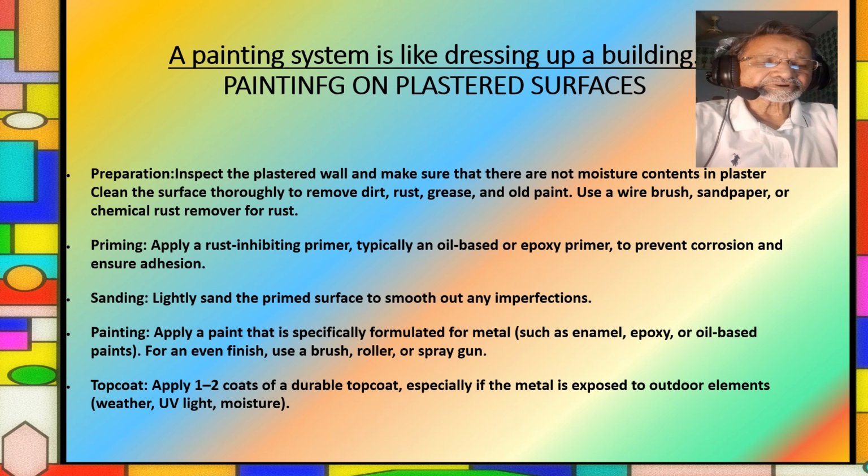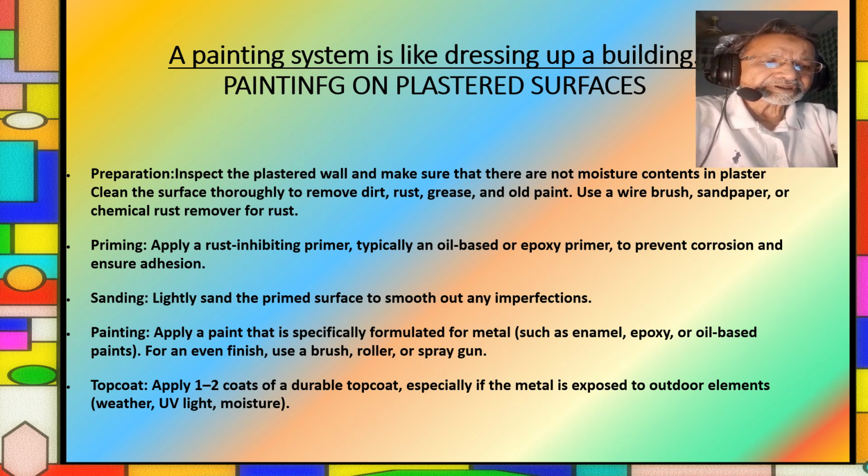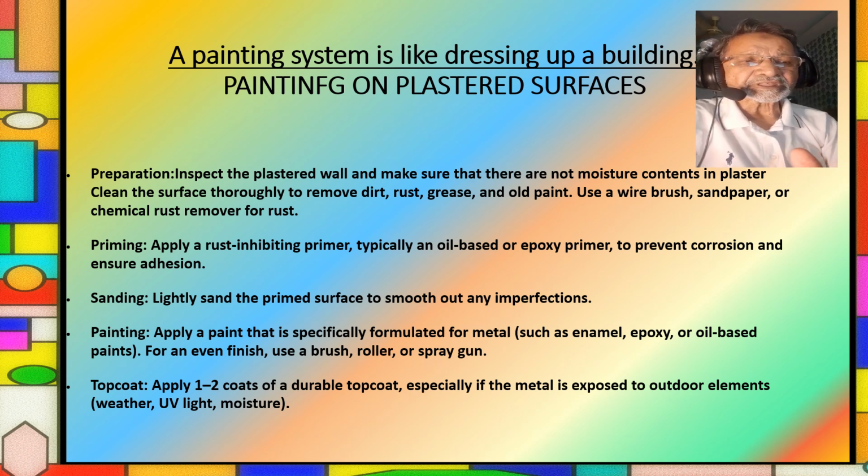Apply the second coat or normal coat. Once the mist coat is dried, begin applying the main coat of the paint. In each layer of either water-borne or oil-borne paint, stir the paint thoroughly and if necessary dilute it slightly with water in water-borne paints and mix oil additive in oil paints.